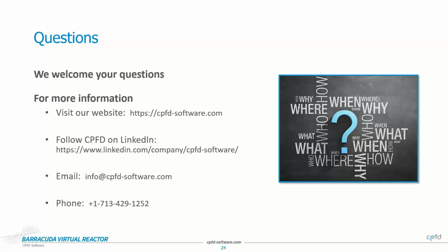So in a case like that, you can definitely use this chemistry rate limiter. And as I mentioned, the spatial profile may not be exactly right, but if that's not your main focus of the simulation, then you could get a 10x or 100x faster simulation and be much more useful, much quicker to iterate on by using that.